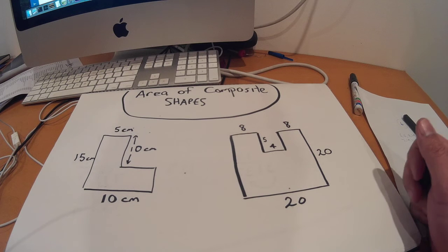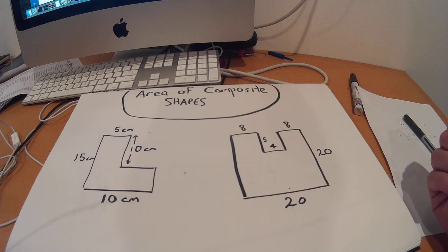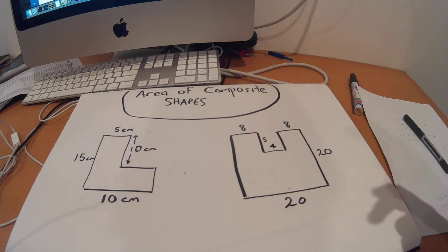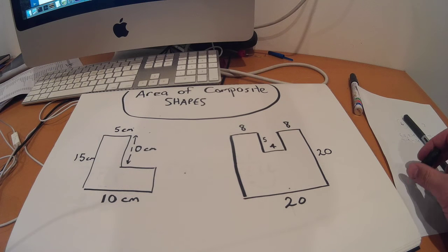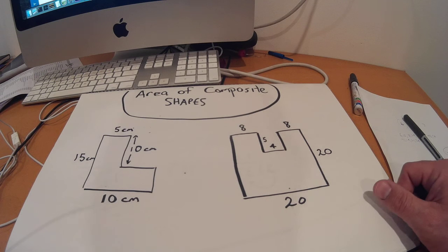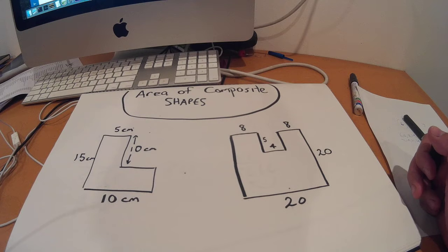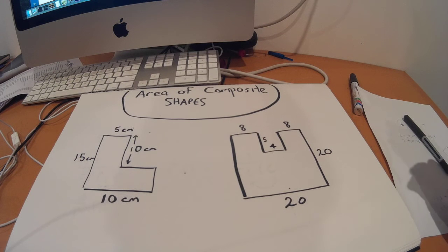Now, method one is what I call the additive method, where you're breaking up a composite shape. And composite just means it's made or composed of different shapes. So when you see that term composite material, which you'll see used for Kevlar and stuff like that, it just means it's layered in different materials to give it added strength. So you'll see that word used a lot, composite. So in this case, a composite shape is a shape that's made up of a number of different shapes, and the way to simplify this problem, like all problems, is to break it down into smaller steps and more easily understood things, and you'll be able to solve the problem.